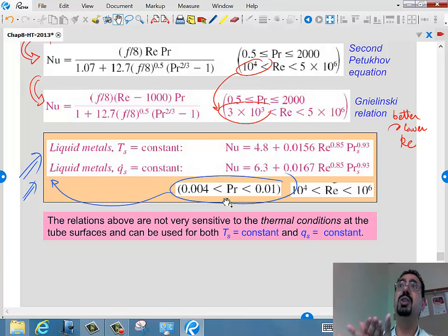And you'll be done. You just get the Nusselt number, and from that you get the h, and you would say Q equals hAΔT, and then figure out, does he ask for the Q or the ΔT or the area? And we said last time, if you ask for the ΔT, that's the worst problem ever. Because the properties require ΔT. So it's basically a lot of trial and error, if that is the case.